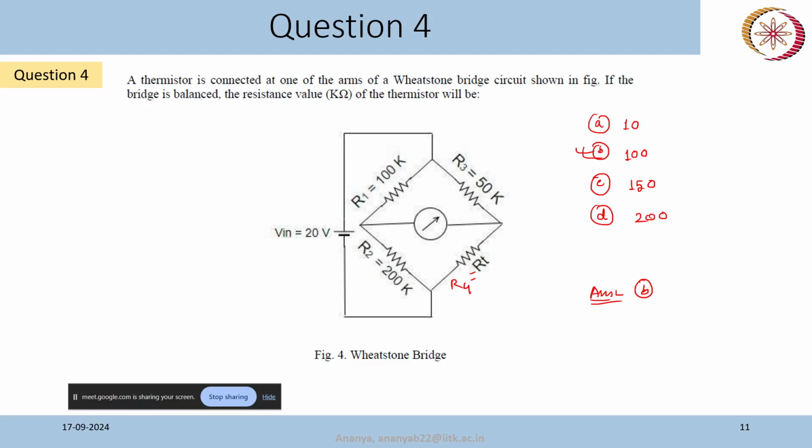So any other variation that will affect all of these resistors will be cancelled out overall. That is the advantage of a Wheatstone bridge circuit. And we often use a Wheatstone bridge circuit to find the calibration curve in case of a resistive sensor, again because that will give us more accurate results.